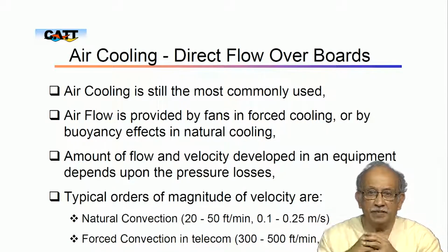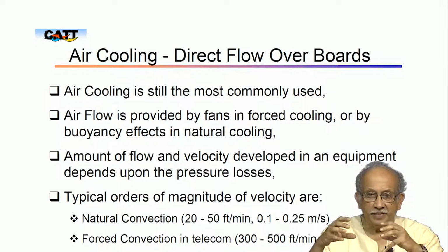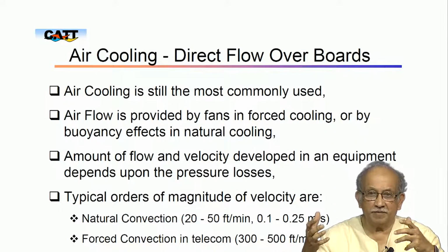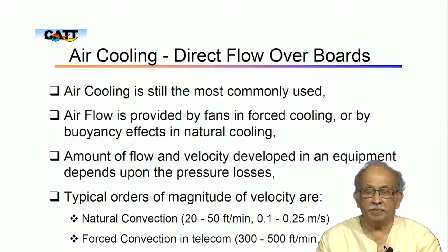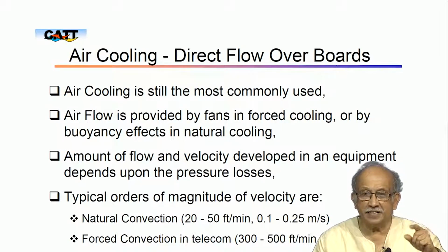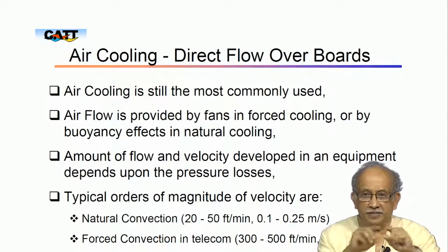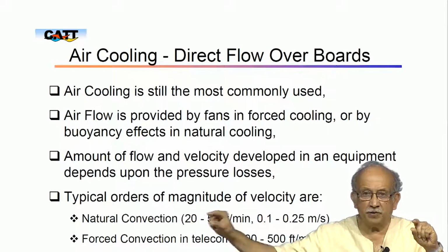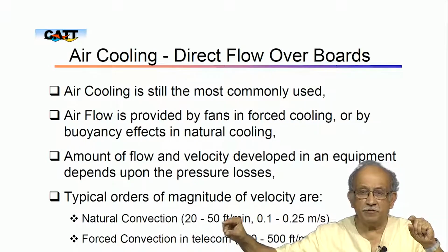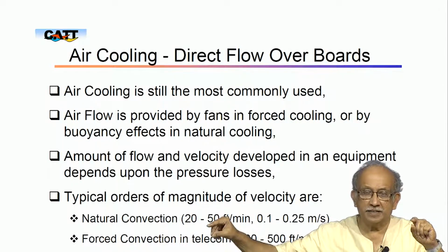In the case of plumbing, you will notice that the requirement of the pump, the water pump, depends on 2 things. One is the head that is required, another is the length of pipe. So, you have this much length of pipe and you know how much resistance it gives per running meter. Easy enough, is it not?